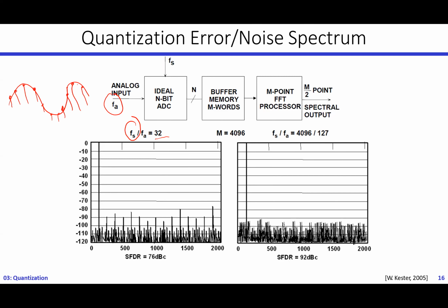Every cycle of your sampling signal will sample your input signal at exactly the same location, because it's just an integer multiple of it. So let's say if your input signal is 1/5 of your sampling frequency, we will keep sampling the input signal at exactly the same location in every single cycle of your input signal. Is that making sense?